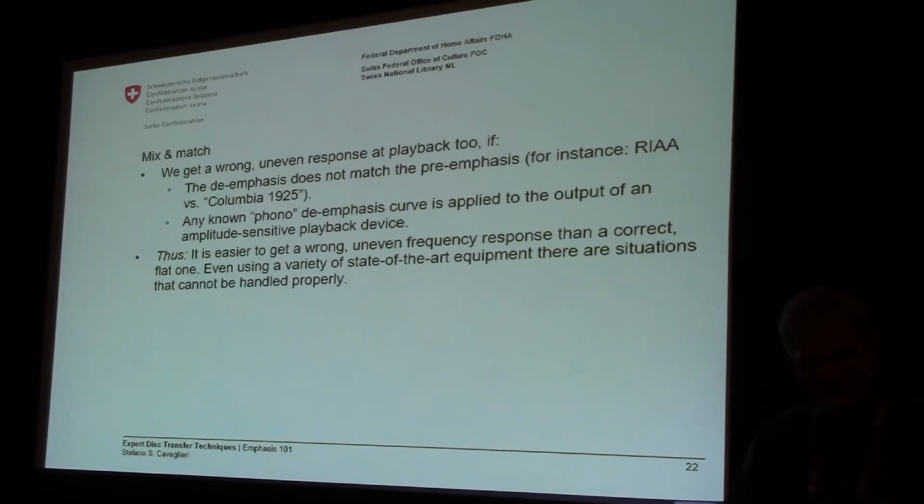But we get a wrong, uneven response at playback too if the de-emphasis does not match the pre-emphasis. If it's cut with an RIAA pre-emphasis and we read it with a so-called Columbia 1925 de-emphasis, we get a wrong frequency spectrum.